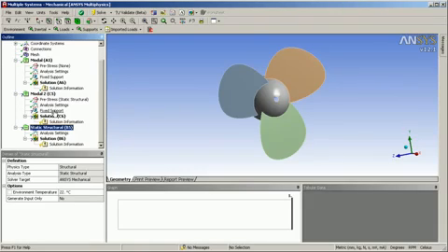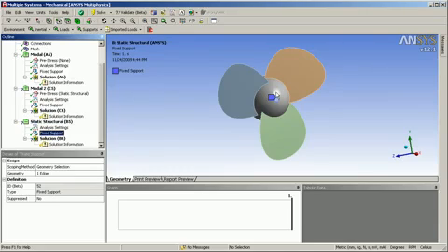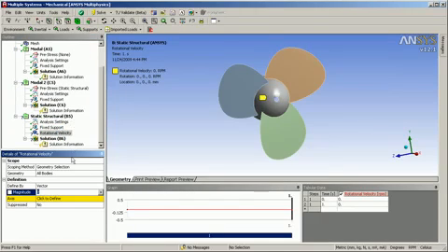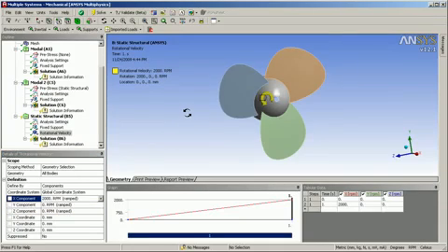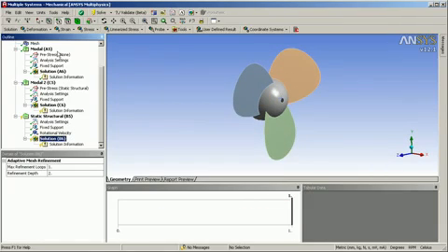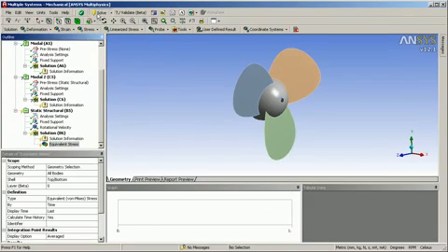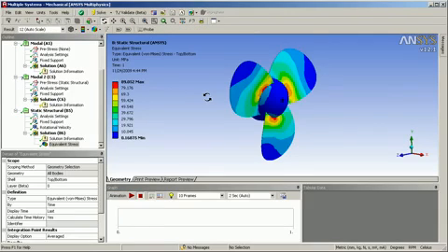I can set up the static structural analysis by dragging the fixed support on that center hole in the fan down to the static analysis and then adding an additional load of a rotational velocity. In this case I want it to be a rotational velocity of 2000 RPM about the x-axis. So you see it's going to be simulating a rotation about the x-axis. And I'll request a stress result so we can review that, and perform this solution. Just to take a look at the stress result, you see here there's 89 megapascal stress in this fan.